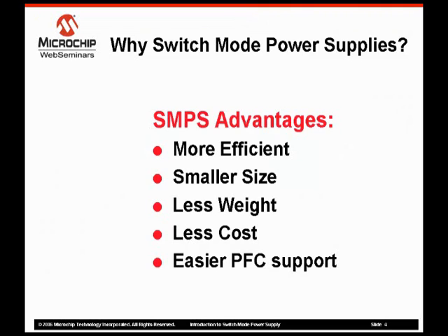Why switch mode power supplies? Switch mode power supplies offer the advantages of a smaller size, weight, and cost while achieving much higher power efficiencies. Almost any product can benefit from a reduction in weight and size. Switch mode power supplies have a more complex circuit design than linear power supplies. But at medium to high power levels, the cost of dealing with high heat dissipation outweighs the cost of a more complex circuit. The improvement in energy efficiency is often a required feature for many products, especially battery-powered items where battery life is a critical selling point to a customer.